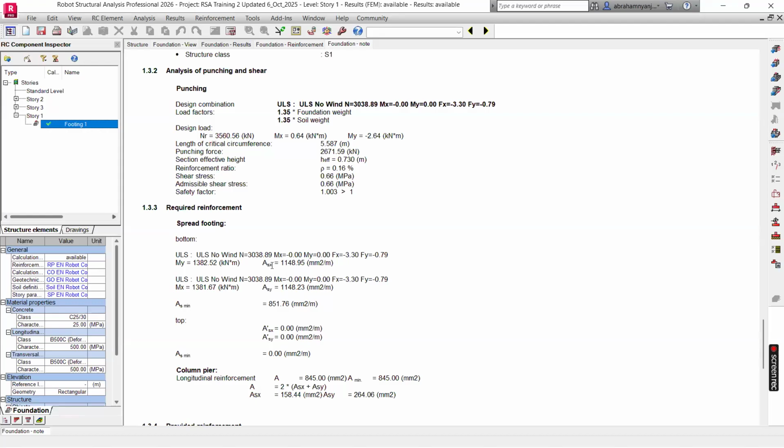So you can see in the X, this is the reinforcement, the area of steel that is required. And in the Y, this is the reinforcement area that is required. The top, this is bottom, the top, you can see there is none, and that is why it is singly reinforced. So it provided T16, there were 52, but now we can go further and check.